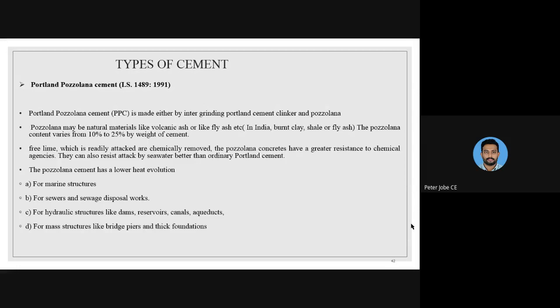So wherever you go, you can easily find these PPCs. And if you go to any hardware shop where they sell cement and request PPC, they will have a huge stock of PPC. Ordinary Portland cement (OPC), that we had discussed earlier, was the first cement that was produced, and the stock of OPC will be very little, and in some cases they won't even have OPC, because no one is going to use OPC nowadays.